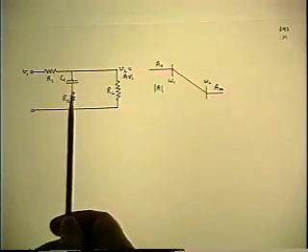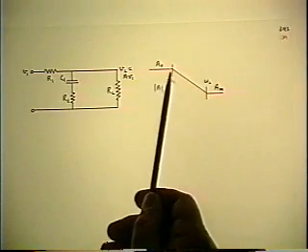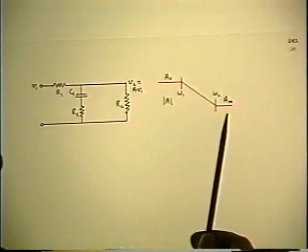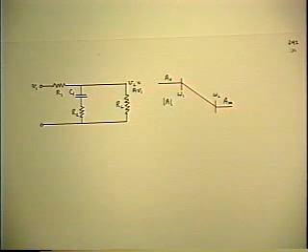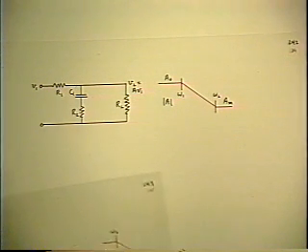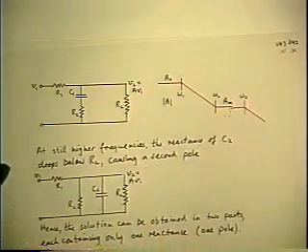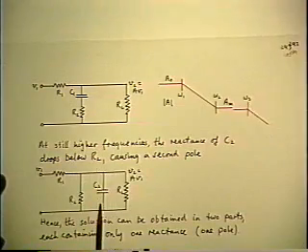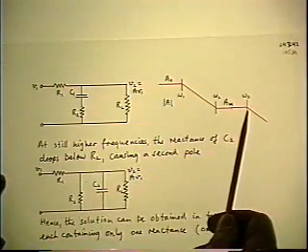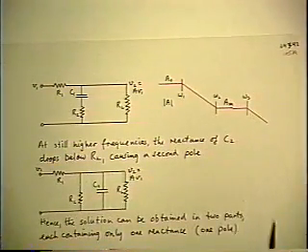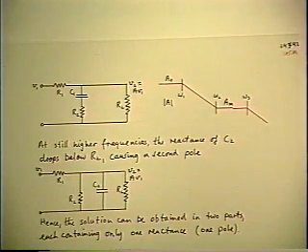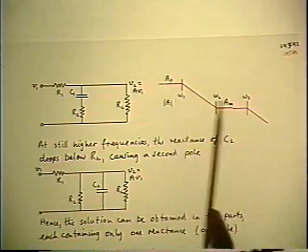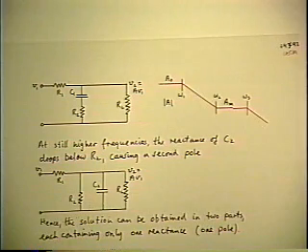In the lower range, only the C1 does anything, and it causes both a pole and a zero. And you can solve that part of the circuit separately. After that, the C1 becomes a short, and then C2 starts to come in, causing the second pole. So qualitatively, before you even write anything, you know that the two poles are determined separately by the two capacitors.